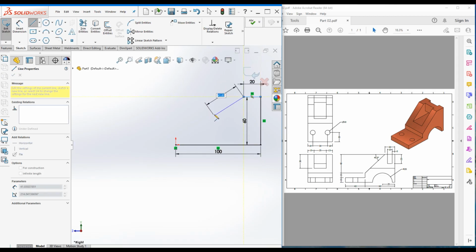And now you have to enter the distance, but here you actually can't enter the distance. It is only the angle. So therefore just click on somewhere here and now move this way and you have to bring it down 10 millimeter. And again this distance you can't really define because you have to align this line with the origin. So I will just click in here and close the sketch and enter 10 millimeter.